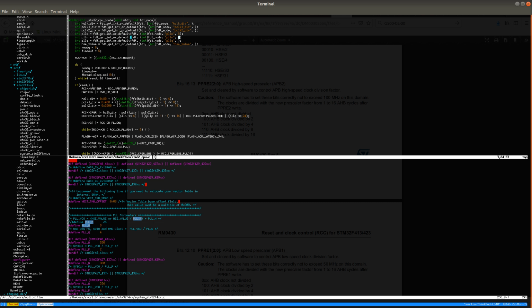Default value for N is the multiplication of that 1 megahertz, which we now multiply 200 times to get 200 megahertz, which is then divided by 2 to get the frequency of the main clock, which will end up being 100 megahertz.